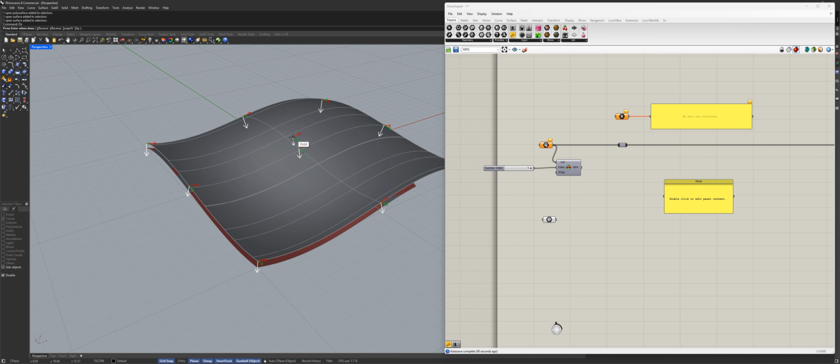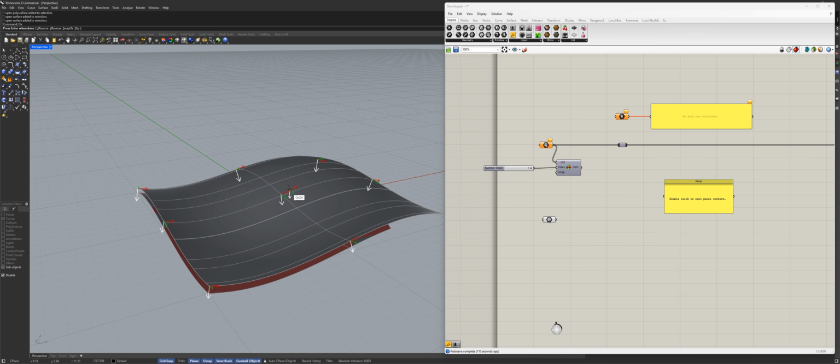What about the x and y? Now, in most cases, in situations like that, Alias, just from experience, flips the u and v orientations, not parametrically, but geometrically. It's not a big issue for us. I just want to remind you, because it will be important when it comes to the planes and the orientations of planes. For now, I don't really want to do anything about the u and v directions. I can swap them, but I don't want to.